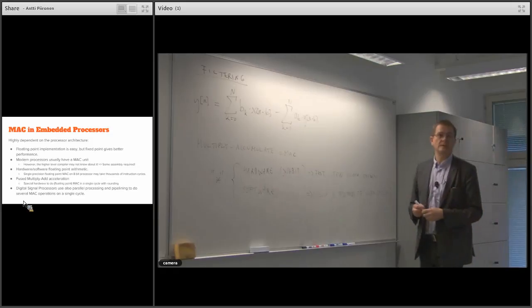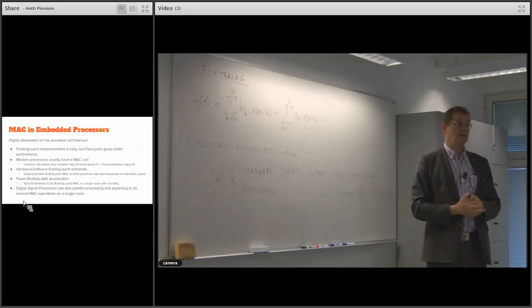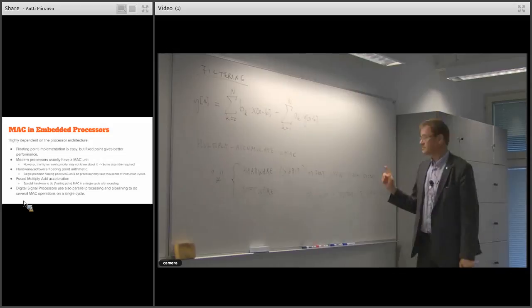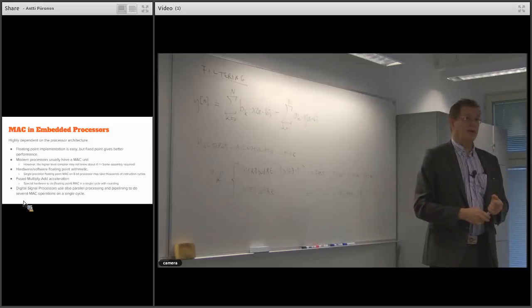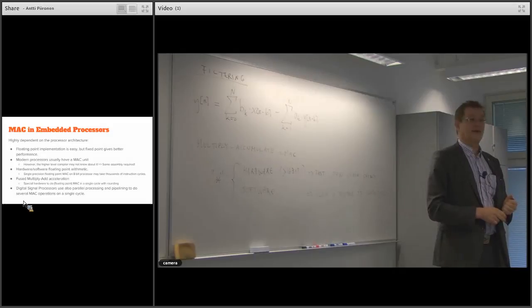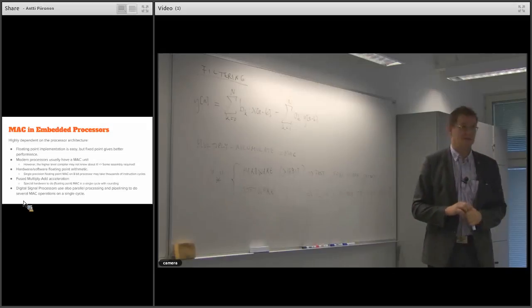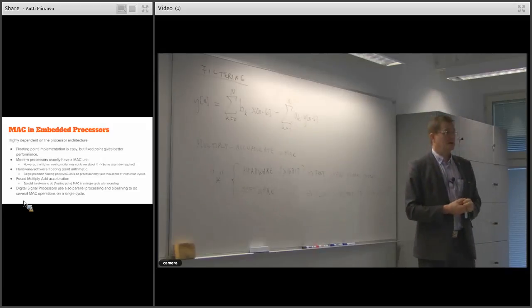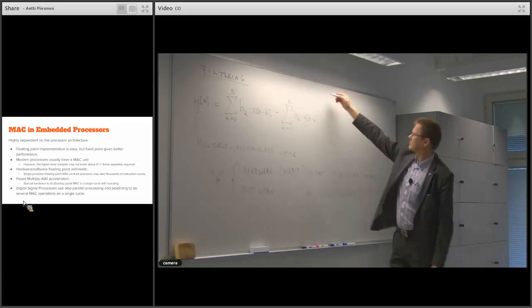Okay. Then also, when you do the multiplications, one issue is so-called fused multiply add. So how to speed up the multiplication with less silicon area. That's actually when you start not caring about the least significant bits. That's so-called fused multiply add. So you have the floating point multiply accumulate circuit, but it doesn't do much of the rounding other than so-called single cycle. It usually just cuts the result, cuts the bits. That's what I'm talking about here.